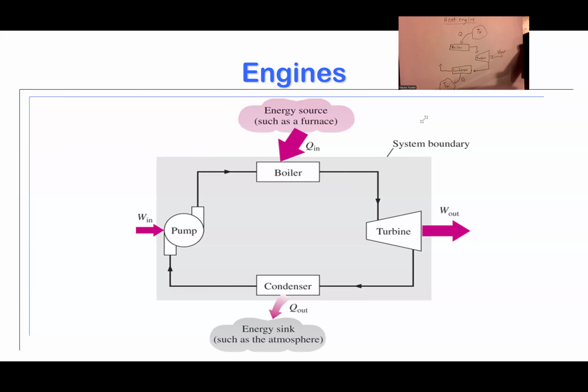in the cycle. Now, I've got low pressure coming out of the turbine. I need high pressure going back in the turbine. There's nothing in the boiler that's going to increase the pressure. I need high pressure here. And in fact, the pressure is just simply going to drop across a real boiler. We're going to assume boilers are ideal and they're not going to lose pressure. That's a fluid mechanics problem to look at the pressure drop from end to end. But all that to say, I need high pressure here. There's nothing from here to here across the boiler that's going to increase the pressure.